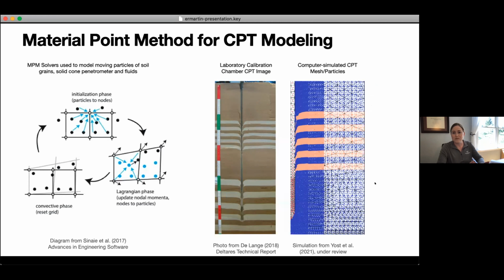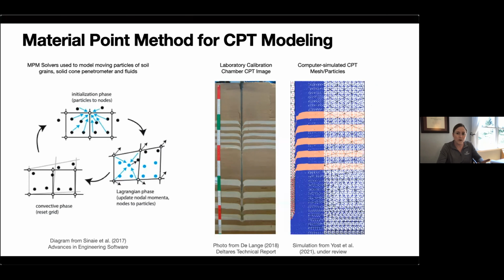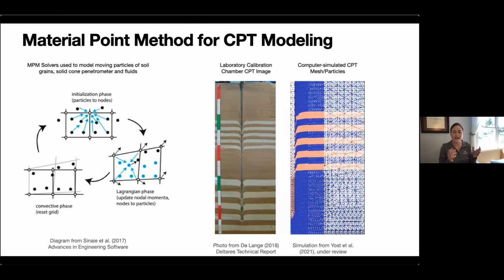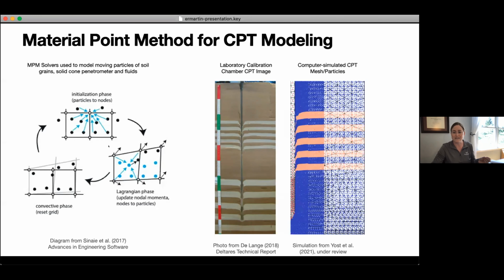So we're actually able to model this process, but it's not totally straightforward how we do this modeling. The method that my colleague Alba Yarrow specializes in is called the material point method. This is a PDE forward simulation method where you maintain both a grid and actual material points. When you have things like soil failure, where many grains of your material are getting pushed around, or where you have a mix of liquids and solids getting pushed around, this tends to work a lot better than some other methods.